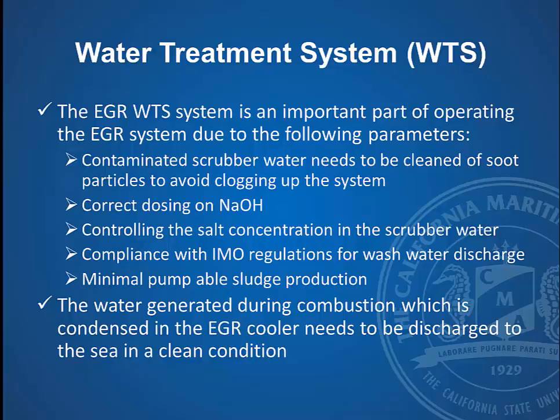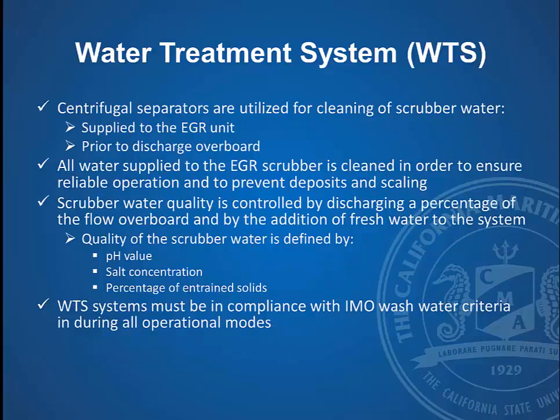production. The water generated during combustion, which is condensed in the exhaust gas recirculation cooler, needs to be discharged to the sea in a clean condition. Centrifugal separators are utilized for cleaning of scrubber water that is supplied to the EGR unit and prior to discharge overboard. Now, these separators look very, very closely like an oil separator or a fuel separator, and are produced by many